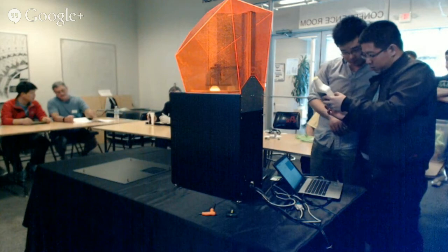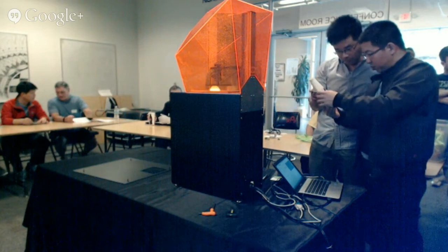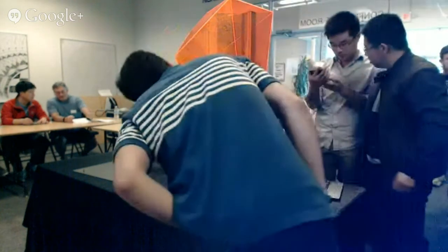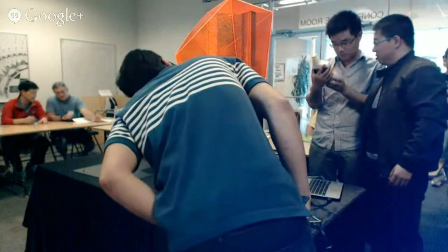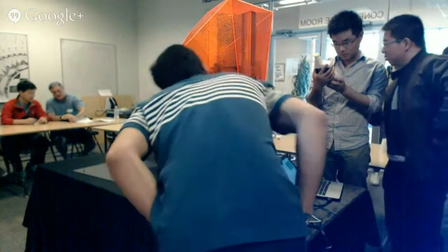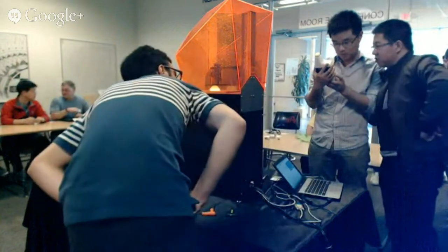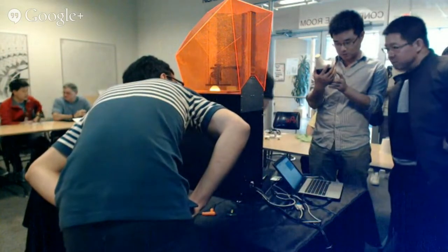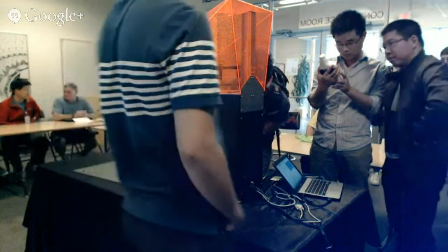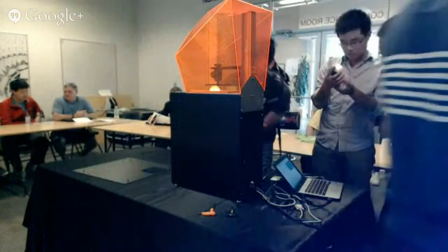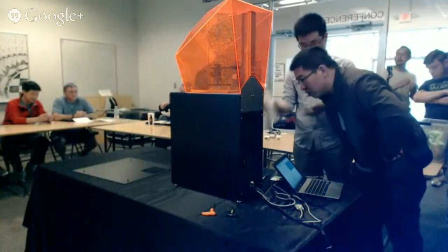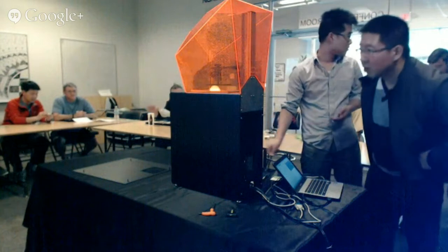If I printed this guy flat on the bed, right? That means the walls here, the same spot is exposed 450 times, right? On silicone, that would pretty much be the end. Same spot, cured at max high intensity, 450 times in a row, you'd be done.